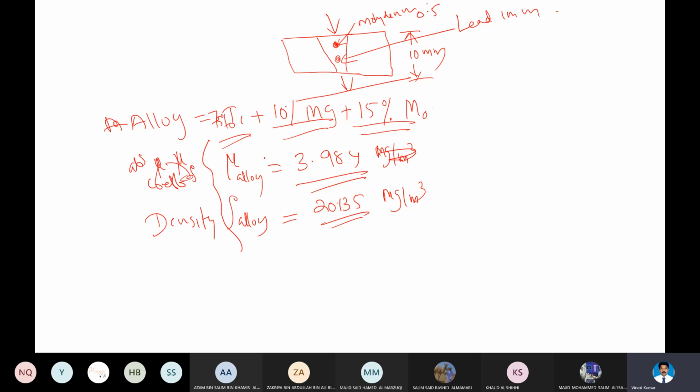The first question was mu and rho that we calculated. Second, the X-ray is passing through a perfect weld. Imagine there are no inclusions here. How do we calculate the X-ray passing through a perfect weld? Ix over I naught through perfect equals e raised to minus mu rho x.